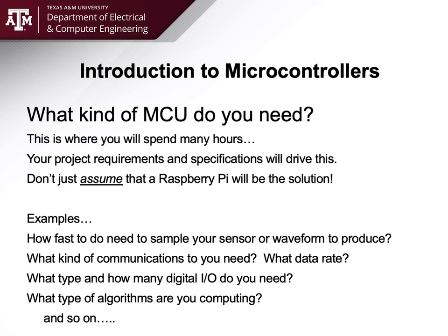It's not going to be able to read the data fast enough and process it fast enough. Once we get into the cache and you're at the actual ARM processing core, oh yeah, it'll handle it just fine. Get on the Neon floating point unit. But you also have bottlenecks, and one of the bottlenecks on the Raspberry Pi is actually I/O. So you need to ask yourself a whole load of questions based upon your requirements.